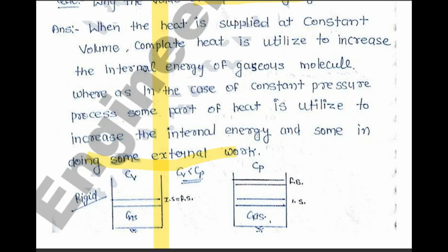Therefore, Q is m Cp delta T. So heat at constant pressure, all the terms are cancelled, just Cp is left out. On the left side Cp is there, on the right side Cv plus some positive term is there. And this results in the fact that Cp is always greater than Cv.